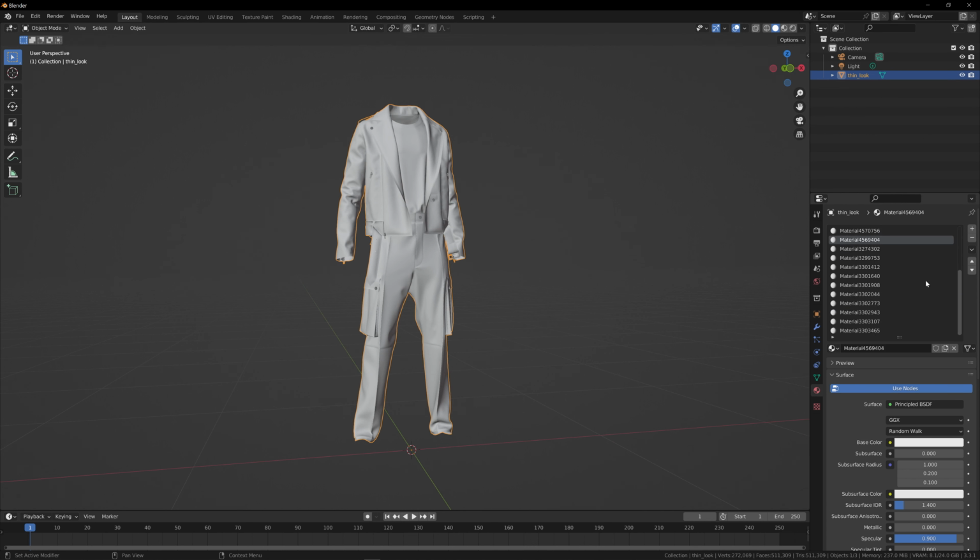And the way we fix this is to start at the bottom of this list of materials. So go all the way to the bottom, choose this subtract icon here on the side, and it will remove each of these material slots and it will shuffle it into the one above. So each of these will now be combined with the one above it. And I go all the way to the top until I see jacket, body, and sleeves.